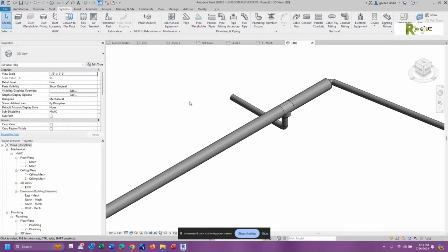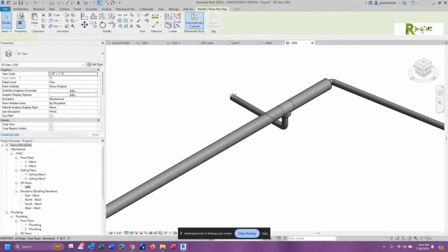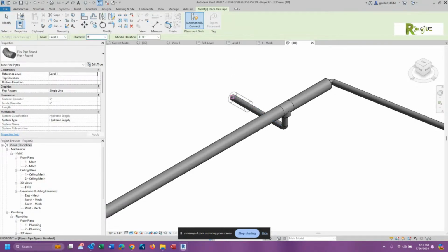And ironically, on this job, the engineers had the exact same problem. What Mike did on the job was he said, that thing's such a pain in the ass, I'm just going to pick on it and delete all of those instances. And everywhere where my pipe actually had reducers in it, it was now broken pipe because the reducer was missing. And that was a good 6-hour change.